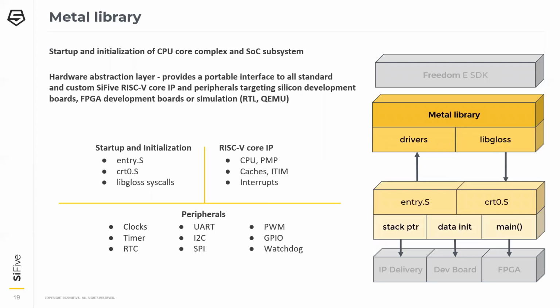As for the hardware abstractions it provides, there are abstractions for RISC-V Core IP to twiddle things in the CPU using CSRs and the like, as well as register interrupts, control the caches, modify the physical memory protection and change the execution modes. From an SoC IP perspective, there are peripheral APIs for accessing common things like GPIOs, UARTs, timers, SPIs, plus many more. And like I mentioned earlier, we're adding more all the time with each release. Writing your software based on these APIs means that they can then be plugged into different frameworks or be used in standalone, portable bare metal applications.